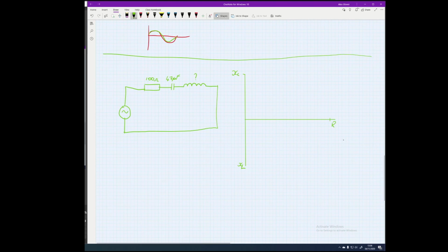So the idea is, like we had before, we got this diagram, we saw it from Pythagoras really, when we got a phase angle happening here. This is Z and this is our angle. So what's happened is here, our normally just resistive circuit, this phasor has been rotated counterclockwise. So the way to get it back in line, to get the phase angle back to zero again, so it's just the resistive element, is to rotate it clockwise.